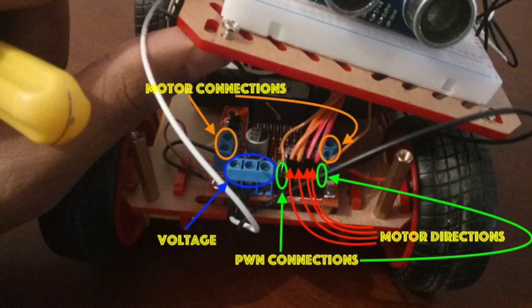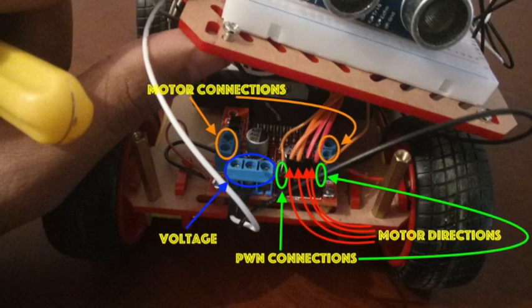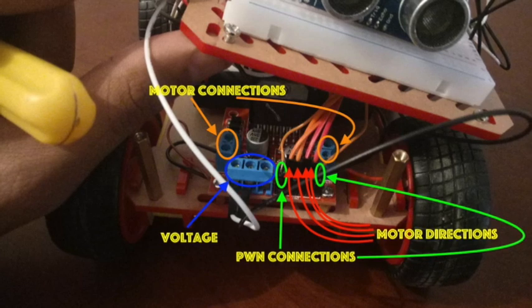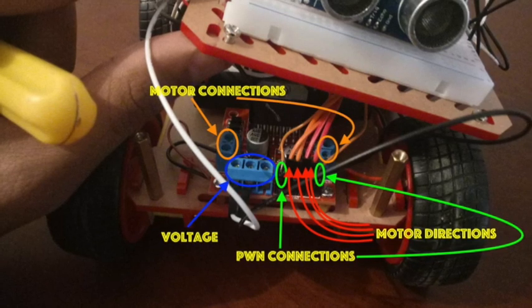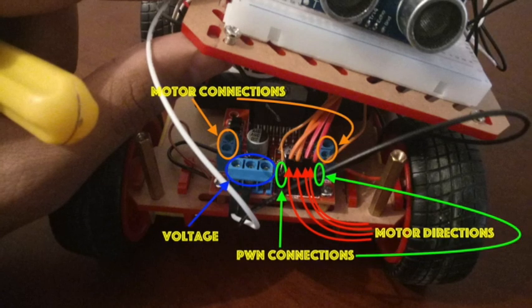Finally, these 2 pins for each motor were used to provide the direction of the motor. One of them must be high, the other must be low, and if we reverse them, the motor direction is reversed. If both are low, the motor stops moving.